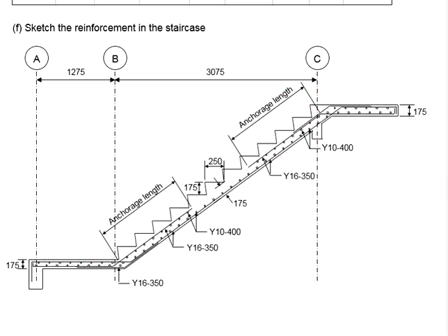One more thing about the layout of the reinforcement, especially for the landing here. If you see the arrangement of the landing beam, instead of having the landing beam here, now the landing beam happens here. This leads to a situation where this part ends up being a cantilever. You have to be extra careful with the cantilever slab. For cantilever members, you will expect negative moment throughout the entire span.